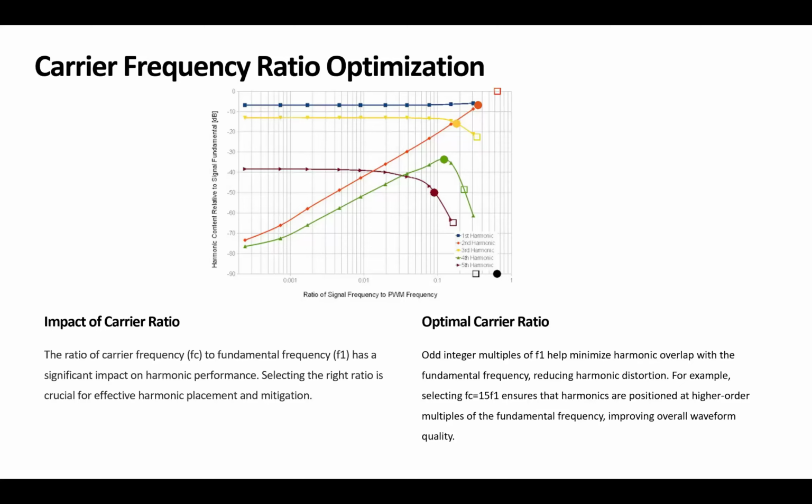the distortion with a parameter that we define named THD, total harmonic distortion, and we use the components, the values in Fourier series, use them in order to define the relative distortion of harmonics to the fundamental. Okay, and we normally represent THD as a percentage value.